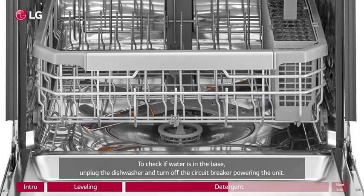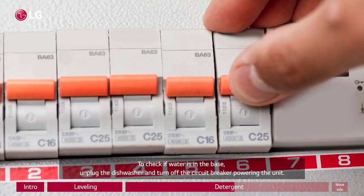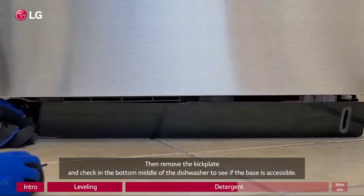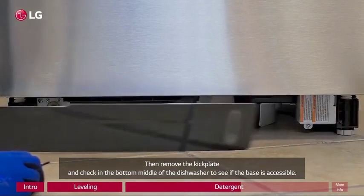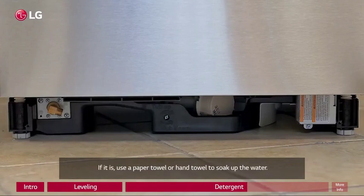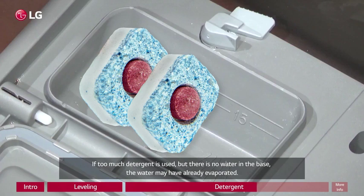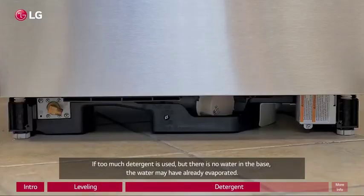To check if water is in the base, unplug the dishwasher and turn off the circuit breaker powering the unit. Then remove the kick plate and check in the bottom middle of the dishwasher to see if the base is accessible. If it is, use a paper towel or hand towel to soak up the water. If too much detergent is used, but there is no water in the base, the water may have already evaporated.